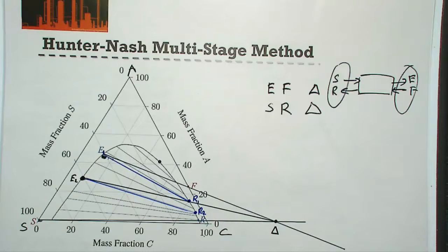So does that make sense? That we go operating line, equilibrium line, operating line, equilibrium line? Yes? No? Yep. So, okay, we know that the next extract must be, due to the flow difference, joined using the same operating point.